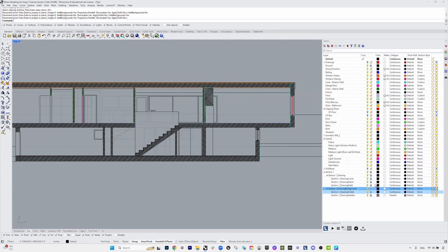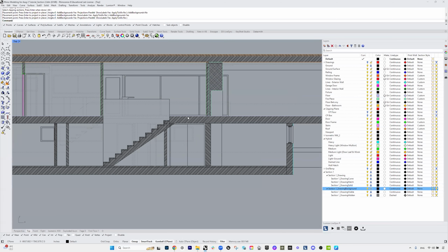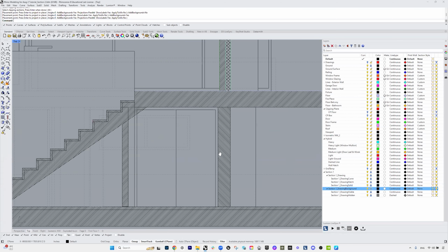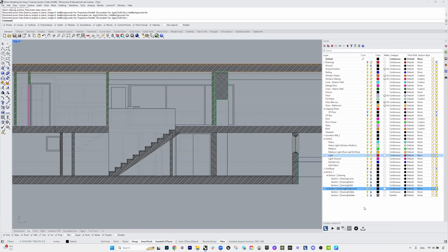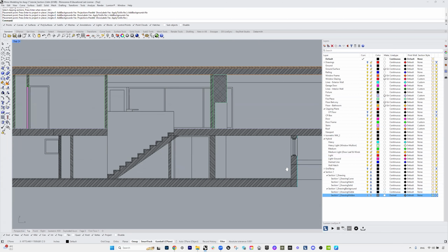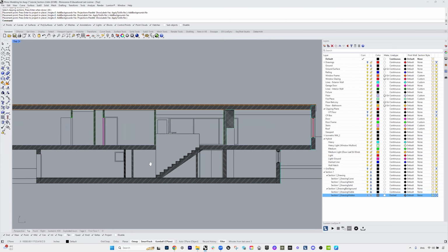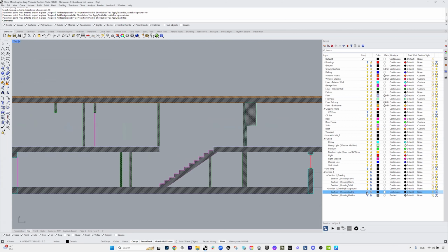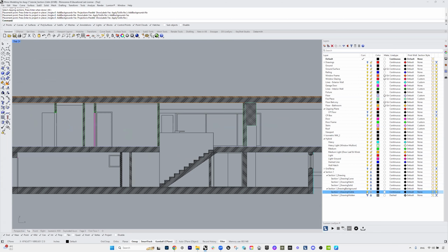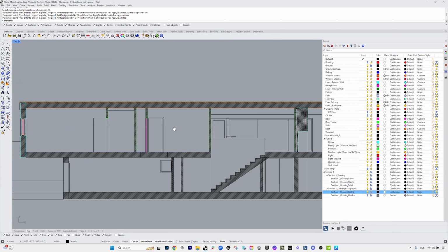The background includes the visible and hidden. The hidden is these dash lines that are not visible in those sections. In general, we don't really need those hidden, so I'm going to turn that off. But these visible lines on the visible layers, we definitely want to have here.